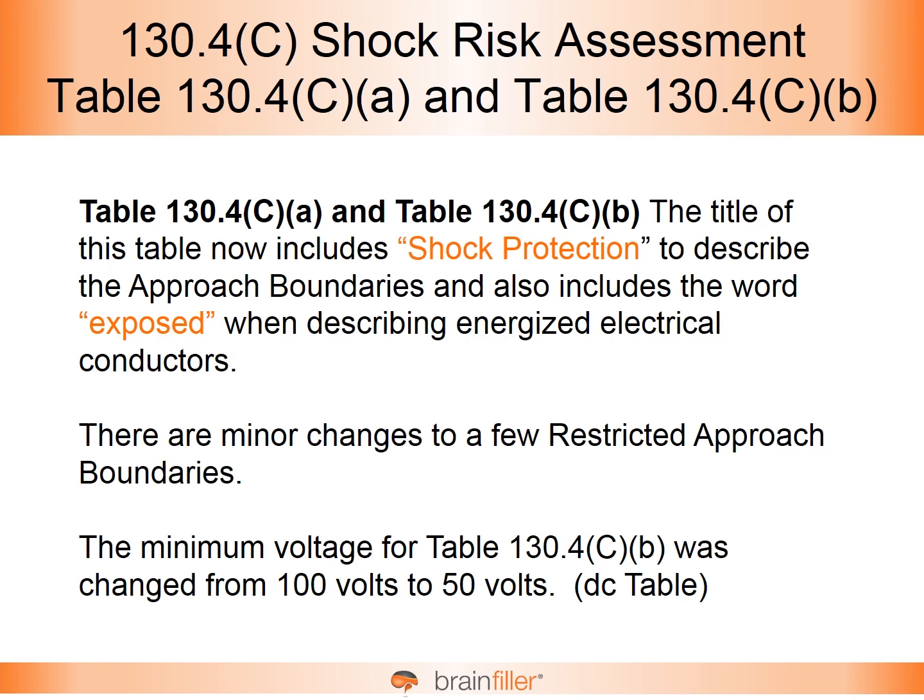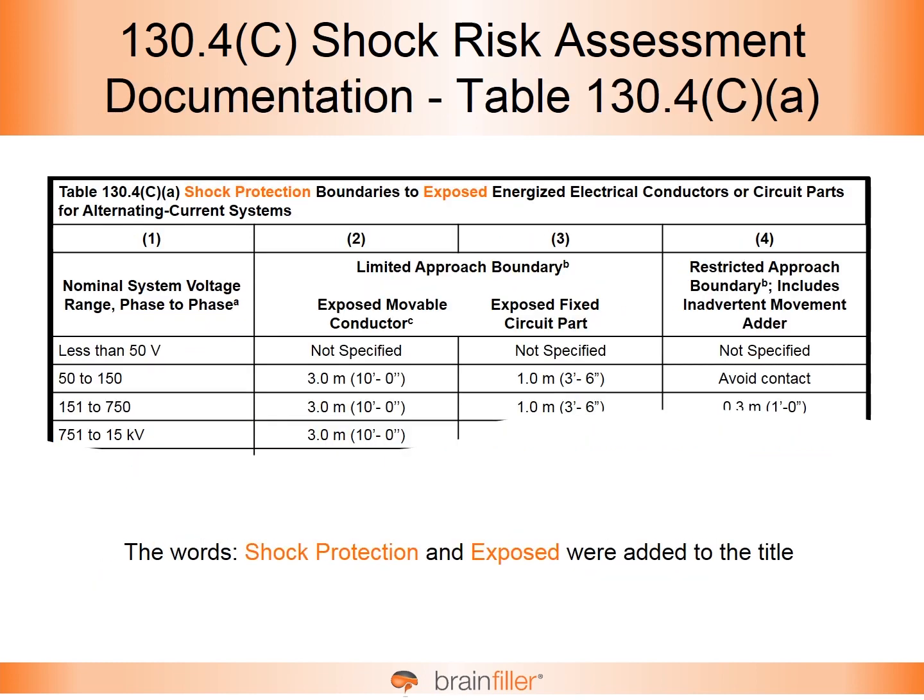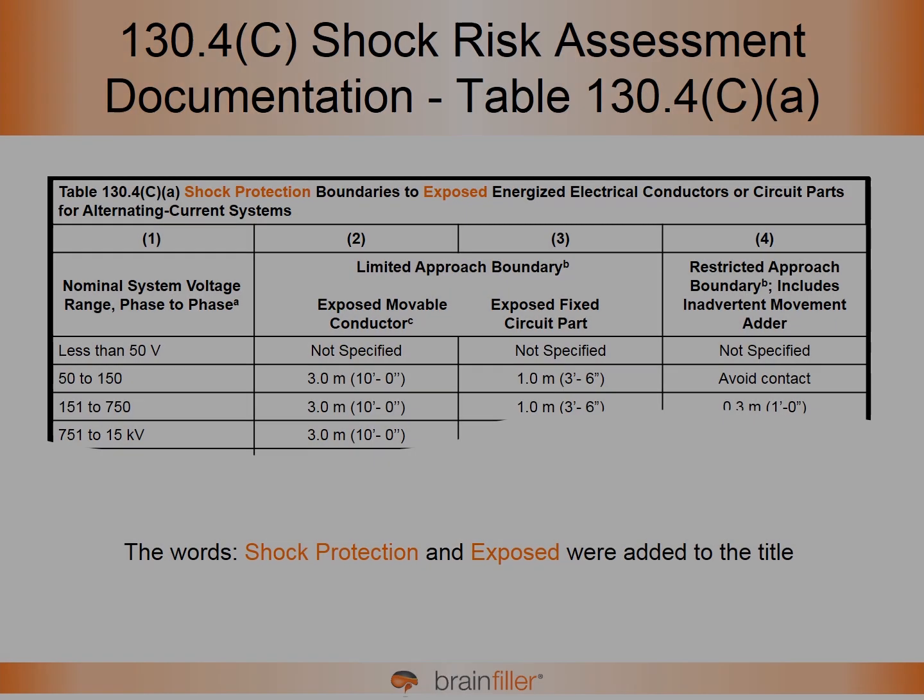130.4C, table A, is an illustration of the new words shock protection. So it now says shock protection boundaries, and the word exposed energized electrical conductors. So the words shock protection and exposed were both added to the title of this table.